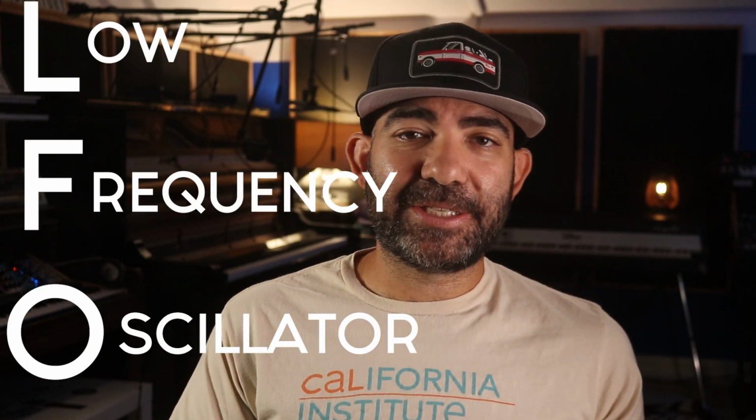The last thing I want to kind of throw out into this is an LFO, or low frequency oscillator. It's just like an oscillator, but the waves are moving so slowly that they don't make sound. They aren't audio rate. Think of an LFO like invisible hands turning knobs for you in a particular way. If we take our LFO and put it in our filter cutoff control voltage input, it will start to turn the filter frequency on its own. It's a really great tool, but this video is getting a little long already, so I think I'll save it for next time.